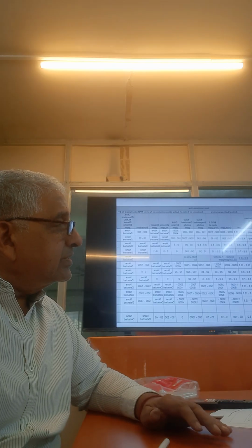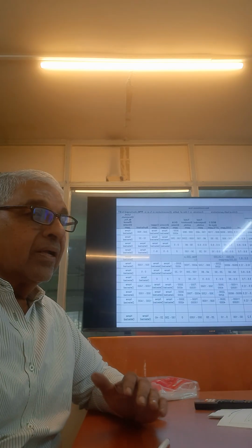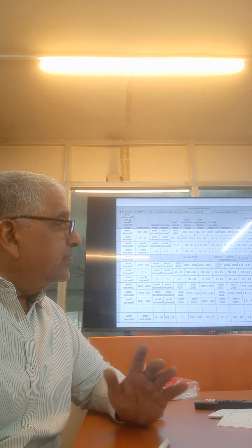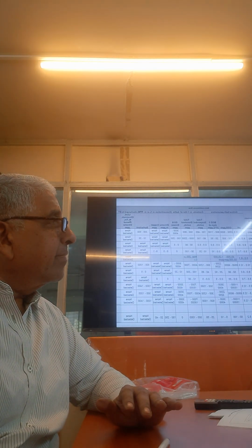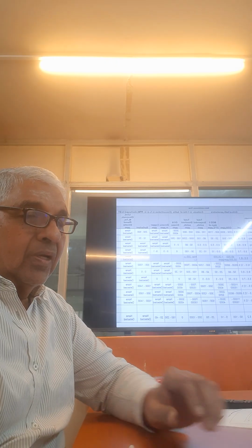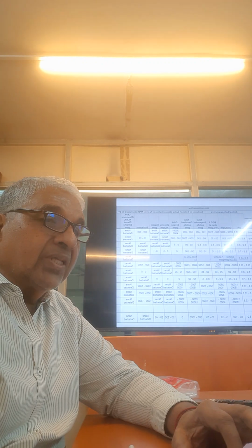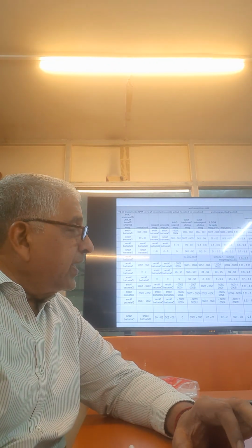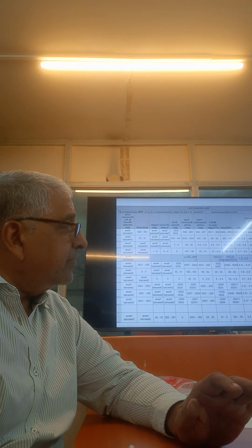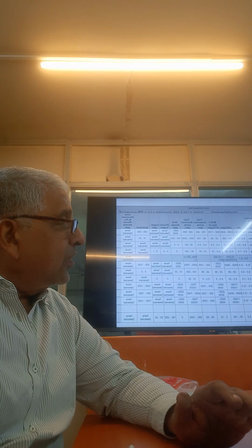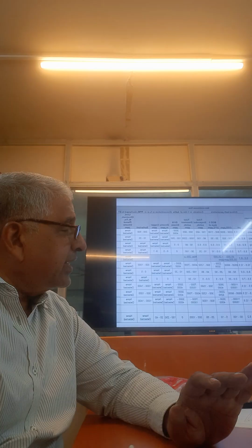The other option is to have another 100 KL separate tank and dump these things, which I feel is not required. You cannot assume alternate days, it can come on the same day. Even if it comes on the same day, it is only 59 KL. So if the previous day they empty the tank up to 70 KL, then they can store it. This is a decision you have to take. You can have another 100 KL extra tank, there is no problem.